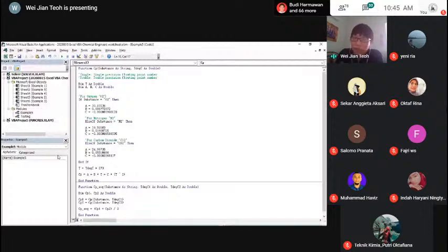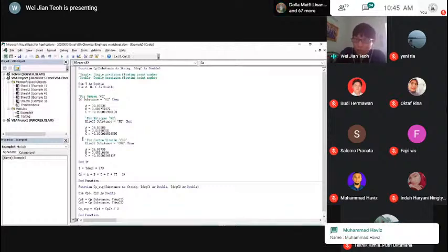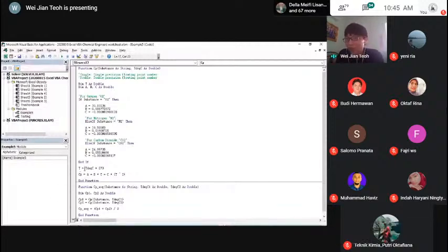I have 100 sheets, 50 sheets, 20 sheets, it doesn't matter. I can access it directly. This also means I can use the CP value for other calculations. For example, if I want to calculate the enthalpy, I can write an enthalpy function in VBA that uses this VBA CP value. It's actually very easy because once the code is there, I can refer to it from other bits of code. That's what makes it very convenient.